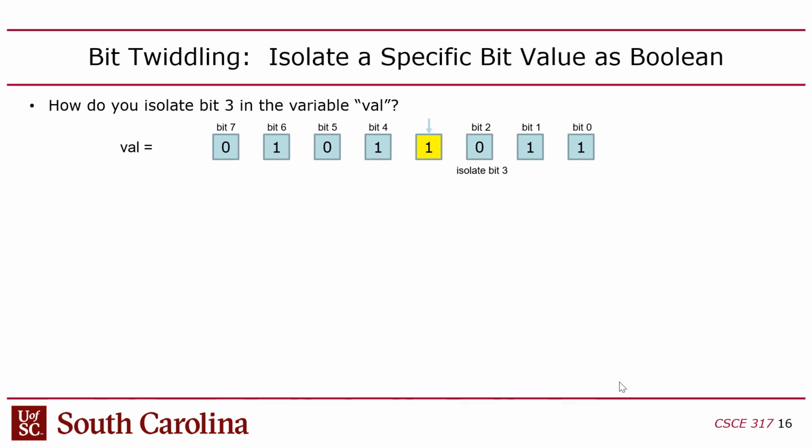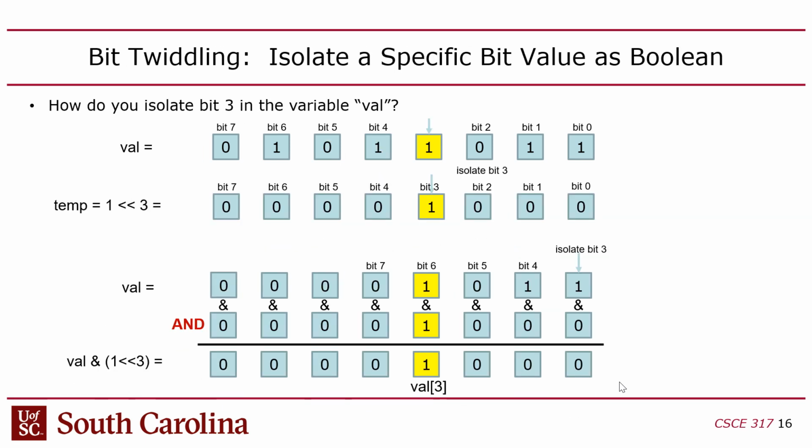Yes? Well, I just want to let you know that those examples are not hard-coded. You can have other approaches in your labs. For example, in this example, you could shift 3 bits to the left, and then OR with the value, and then shift it back if you need it in the first position. So you can use those examples on the slides, but don't be afraid if you don't use them. You can come up with your own solution, and if that works, that's fine. There are other ways to do it.